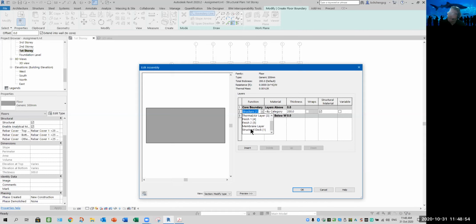Okay, because some have a mixture of steel and concrete together. So they take it as the 1, 5, 4, 3. All these, remember, are known as priority. Meaning what? When components join, the one identified as high or highest priority will cut through the low priority. So remember, meantime, we only have one component added, so no need. Okay, so if one, I pick OK.